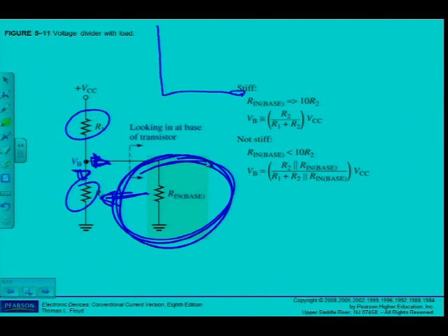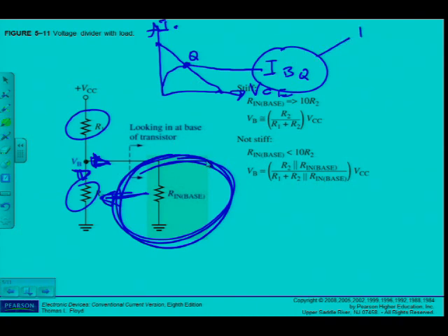If I go and look again at my characteristic curve, my transistor of IC against VCE with my load line. Now I've done a very careful design. I've designed my circuit so that VB gives me an IB, which gives me a Q point in the middle of the load line, my IBQ. This IBQ is determined by VB. So if my VB doesn't give me 5 volts, it only gives me 3.3 volts, what's going to happen with my Q point? It's not going to be in the middle of the load line.